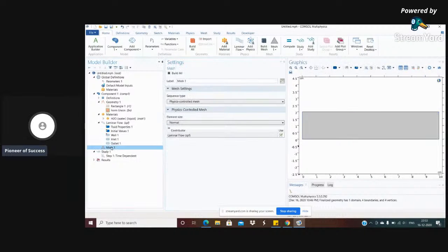So now the important part is meshing. So we click on okay, so there are several kinds of meshes available. There are some inbuilt options. So whenever we learn some simulation or any device we want to use, we prefer to go with the default options initially. Once we become familiar with the software, then we click on several parts, we learn the software and go ahead. And similarly here also, whatever is defined by default, we'll be sticking to this, and this is normal size mesh element, and we stick to this, and we click on build all.